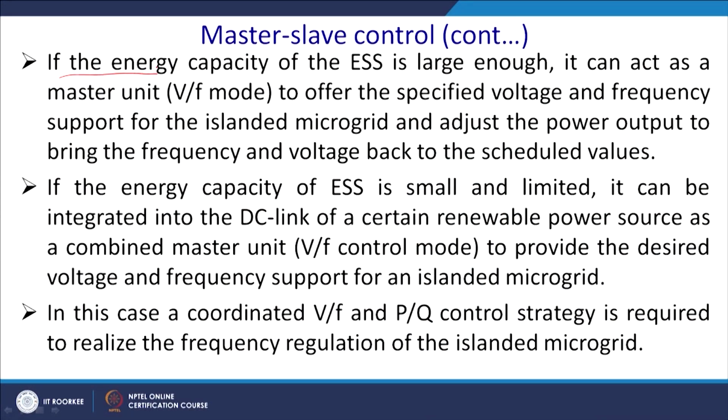Now, if the energy capacity of ESS is large enough, but that comes with a cost, please keep in mind, it can be set as a master unit in the V/F mode to offer the specified voltage and frequency support for the islanding microgrid and adjust the power output to bring the frequency and voltage back to the scheduled values. So, that is something you have to keep in mind: if you want to make your storage element a master, the capacity of the storage element will be quite big.